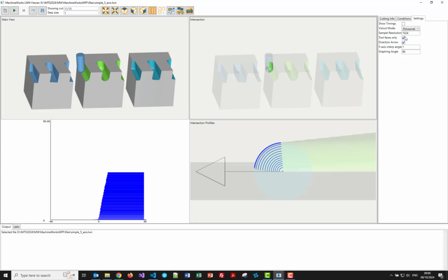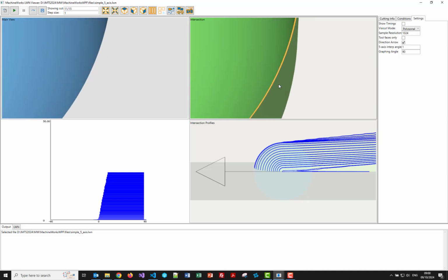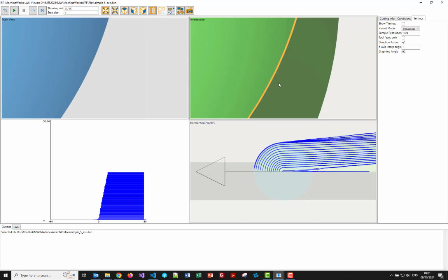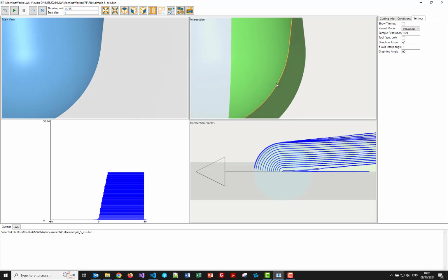So we've got a very thin cut here. So let's actually look at the intersection solid, and you can see we've got a thin intersection solid. It's the same as it was in the previous example, 0.01 thickness, but what you can see is there's a very clean result here. This isn't something that's been reconstructed from a Dexel or a voxel grid. It's an explicit polygon mesh. It's an explicit Boolean operation of 2 meshes, the swept volume and the in-process stock.